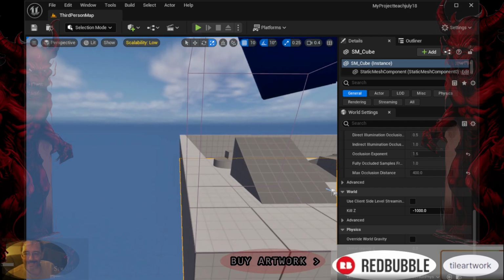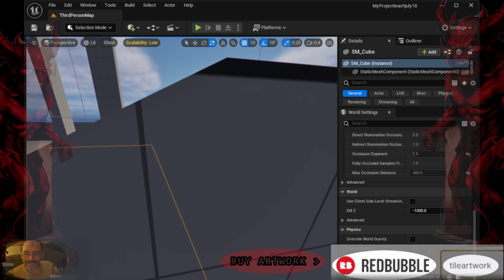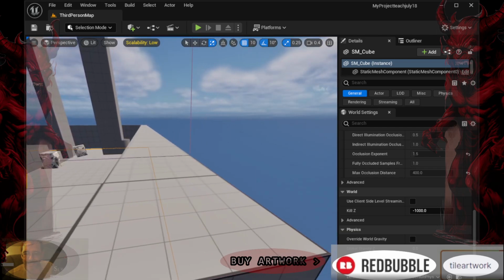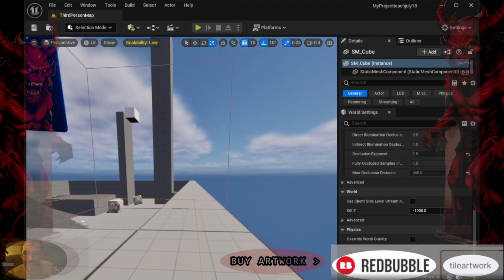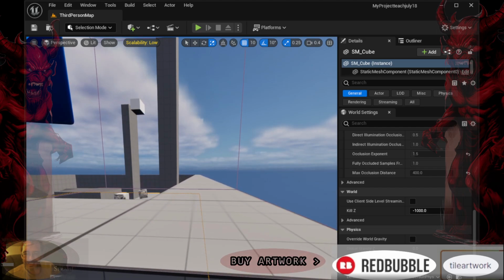Filtering and searching. The output log provides filtering and search capabilities to help navigate through large volumes of log messages efficiently. Filters can be applied to show only specific types of messages, e.g. errors, warnings, or messages related to specific subsystems or components.